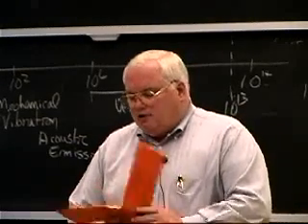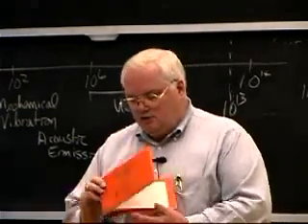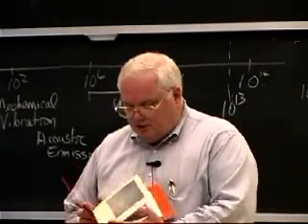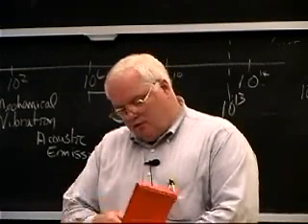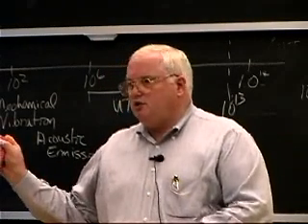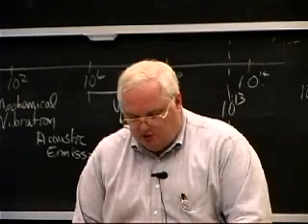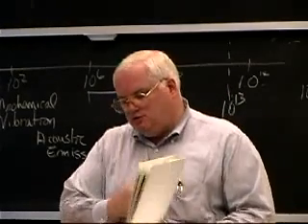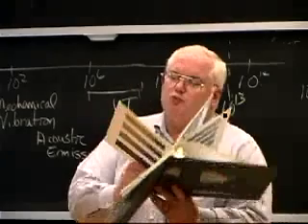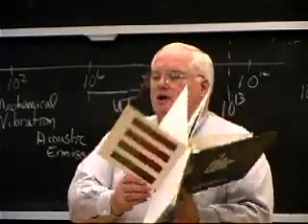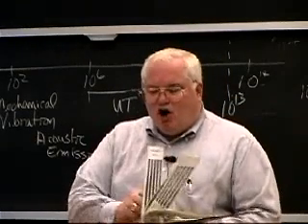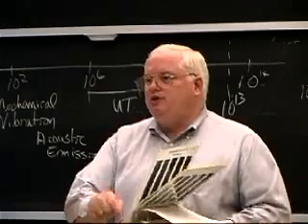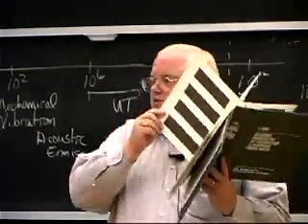This is a little ASTM standard, American Society for Testing Materials, for liquid penetrant inspection. We talked about liquid penetrant, the dye penetrant things. This is reference radiographs for aluminum fusion welds. They're actually real x-rays from real standards, and I can call out a particular level of defect that is shown in these images.